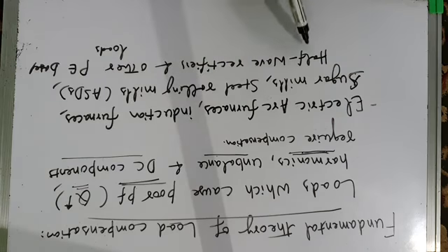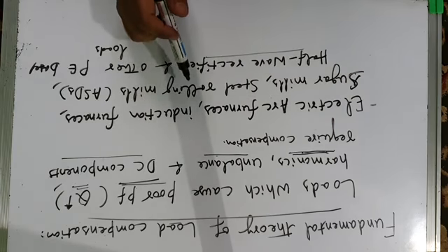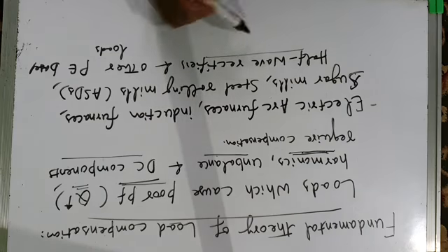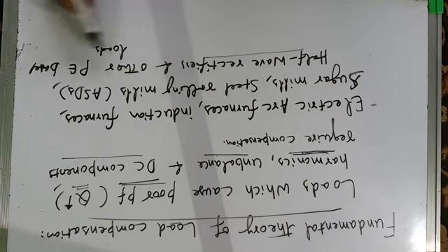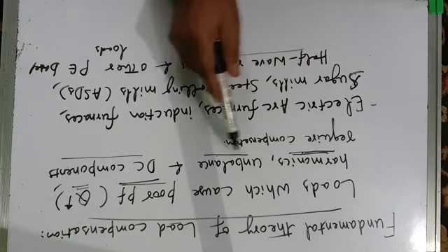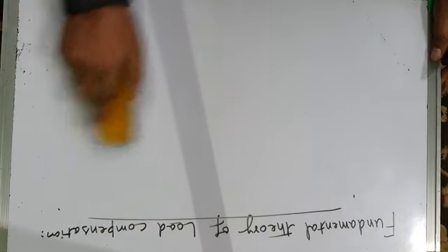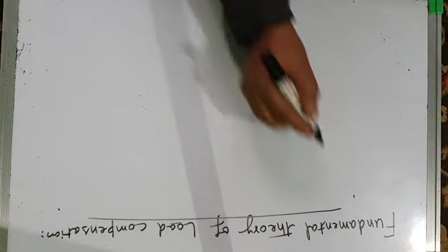And DC components are caused by half-wave rectifiers. Half-wave rectifiers result in the flow of DC currents in the transformers, in the lines, and they cause DC offset, DC current offsets, and DC voltage offsets. And there are other power electronics based loads which are responsible for poor power factor, increased reactive power, harmonics, unbalance, and DC components. So in general, all these types of loads are broadly classified into three categories.